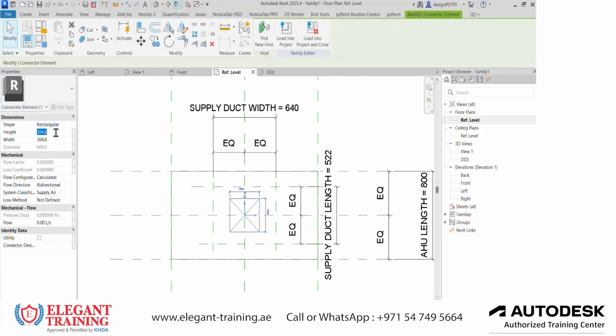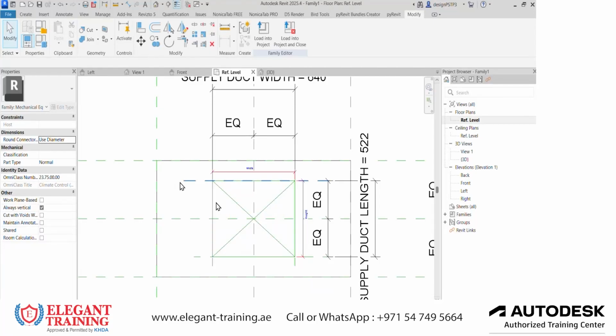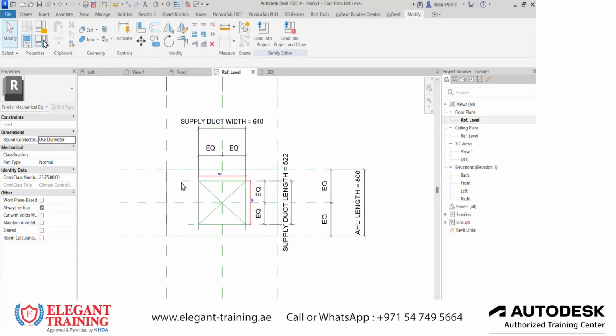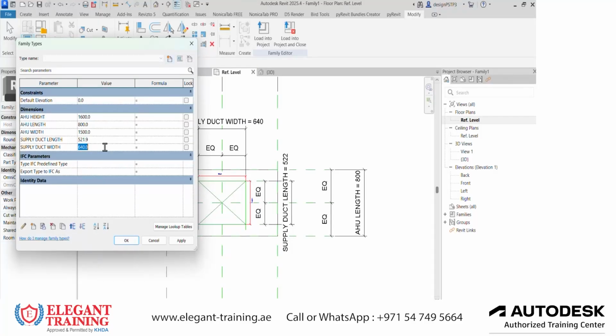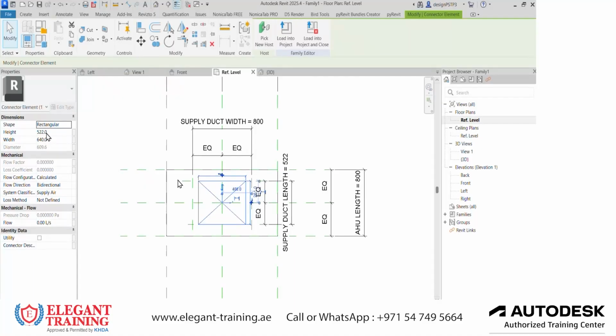Here, 522, and 640. Later on we will change it. To change this one, we need to lock these things, correct? If I change this duct width in the properties, instead of 640 I make it 800. See, only the parameter is moving. Your object is not moving. So the best way is you can change it from here. This is already in the parameter.